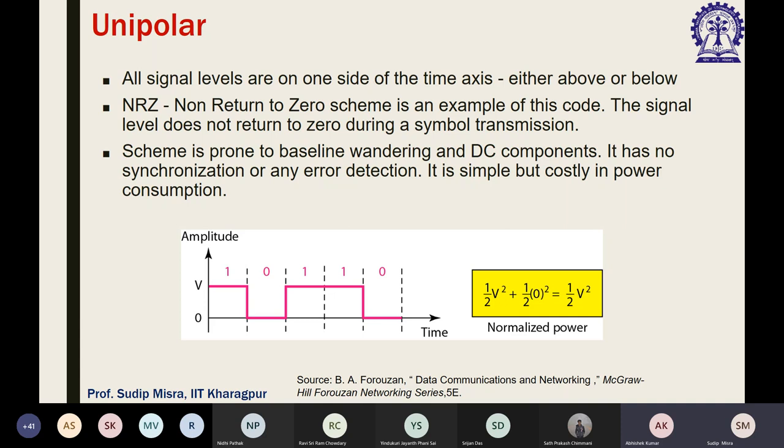Okay. Now, this kind of thing is not desirable. So you need to have some kind of synchronization. So self-synchronization has to be enforced, right? So a digital signal basically has to be self-synchronizing. That basically should include the timing information along with the data that is sent. Okay. So this can be done in different ways. One of the very commonest ways to do it is to use transitions in the signal.